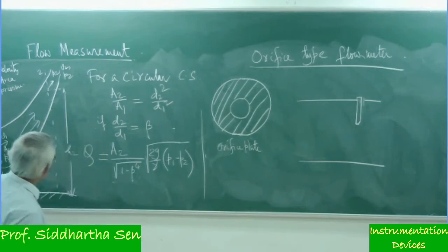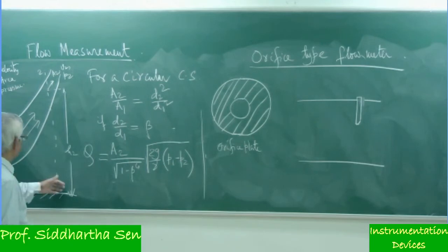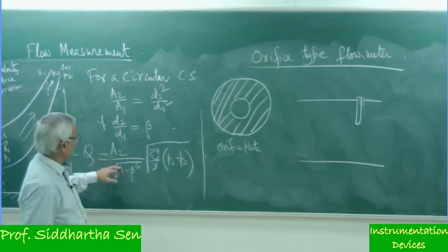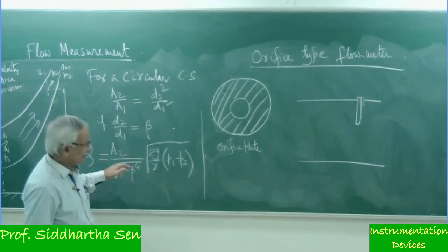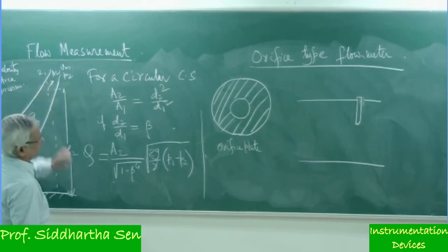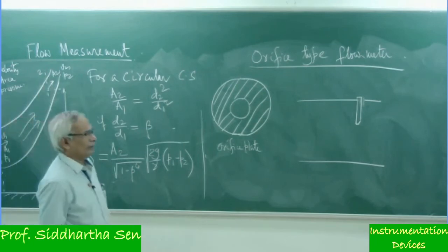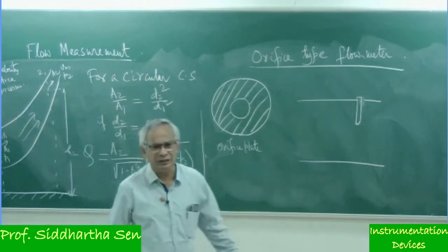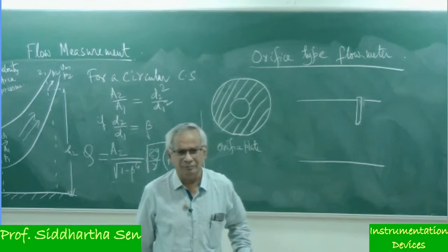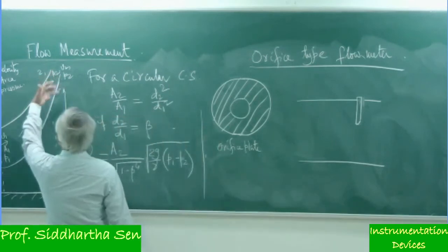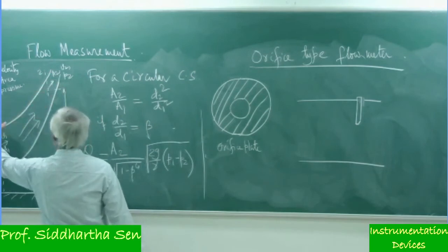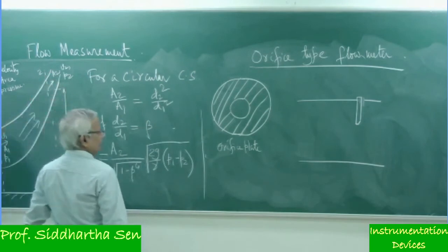But what I wanted to say is, why is the differential pressure created? Because the area is varied. So that is what we are trying to do, create a differential pressure by varying the area. But definitely making this sort of pipeline, where the area is changing, is difficult.